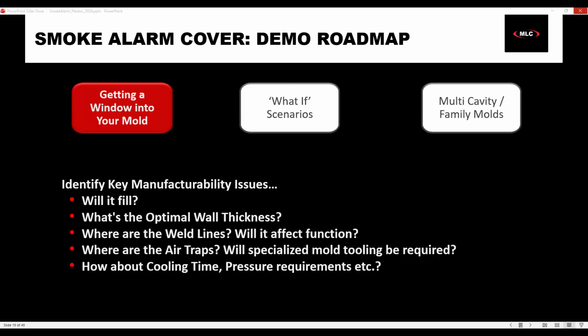So if I'm like, okay, well, maybe we don't want those points, we can just explore tentatively a different location. I can say predict the fill pattern if something is someplace else. It goes through and gives me a rough estimate so that I can see, before I even run a simulation, an idea of what is going to fill last, and I can start iterating very quickly. Now I can choose multiple locations in here as well.